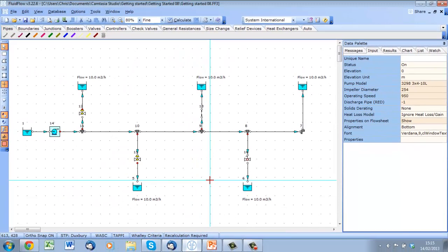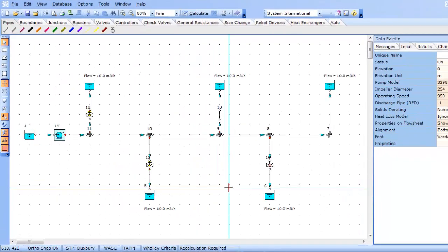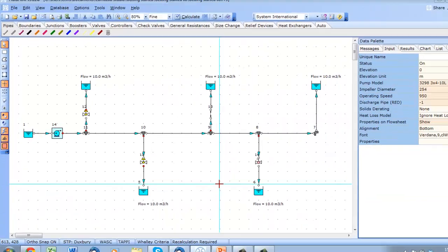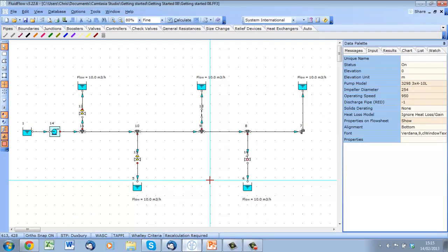Now we have a pump model complete with the curve. We are no longer constrained by our inflow. The pump will deliver a flow based on the system curve and the capacity curve. So we can now reinstate a controller into this leg.